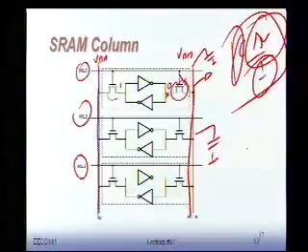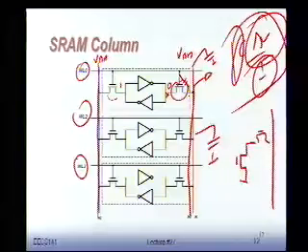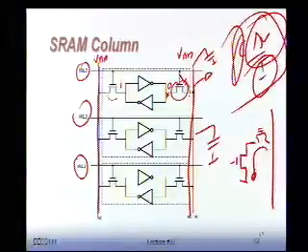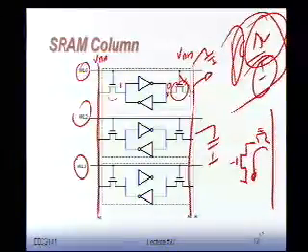So what I have is my NMOS device is on. I have this access device, and I have my bit line. So those two transistors are going to start discharging the bit line. Okay? Not with a lot of current, because that's very small transistors. But slowly but surely going to take charge away from that bit line. Now, if I would have to wait for this whole thing to happen, I could wait forever. So that's not what we're doing.